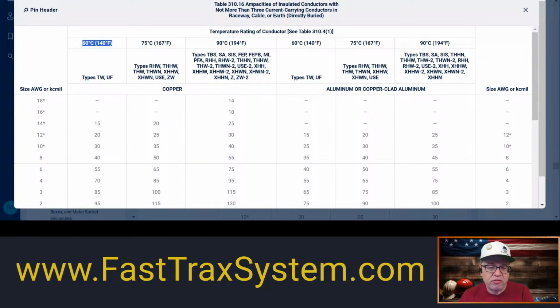Now, that brings us to an interesting topic when it comes to conductors. And I like to point out interesting stuff to everybody, that when you think about a conductor, if it is marked 75 degrees or higher, and even though when you're dealing with the 60-degree column, let's say for THHN, so you may have an ampacity that's less than 100 amps, and you've got conductors that are 14 through 1, and you typically would say, if nothing's marked, I'm going to use the 60-degree column, and that would be true.